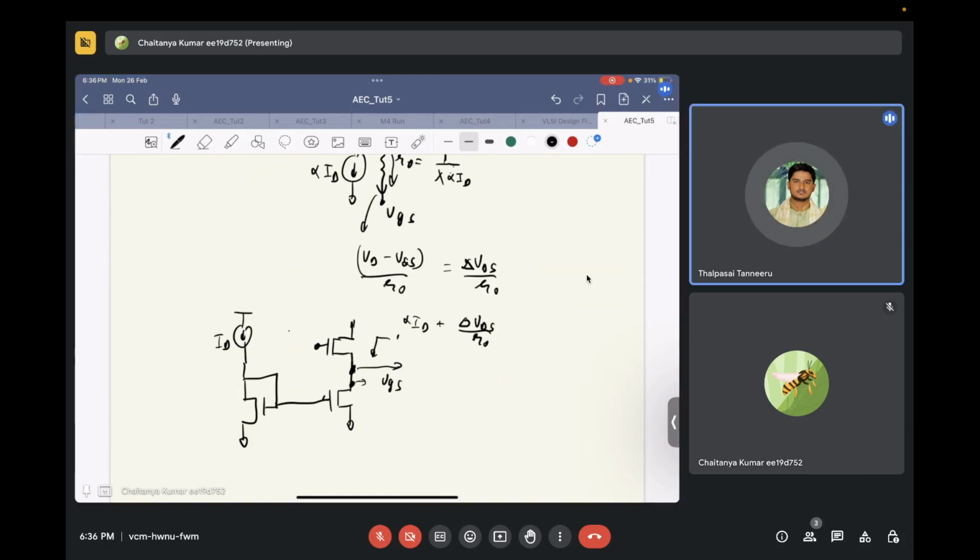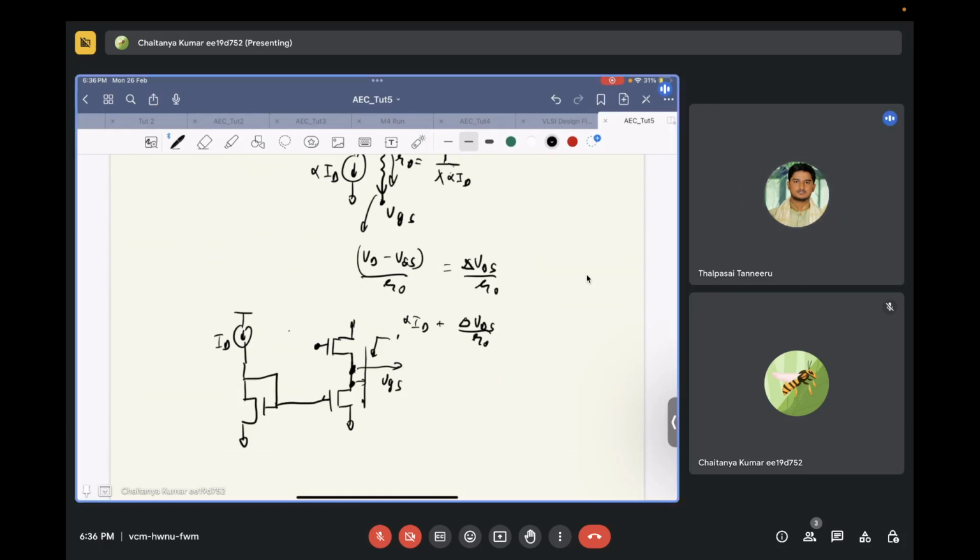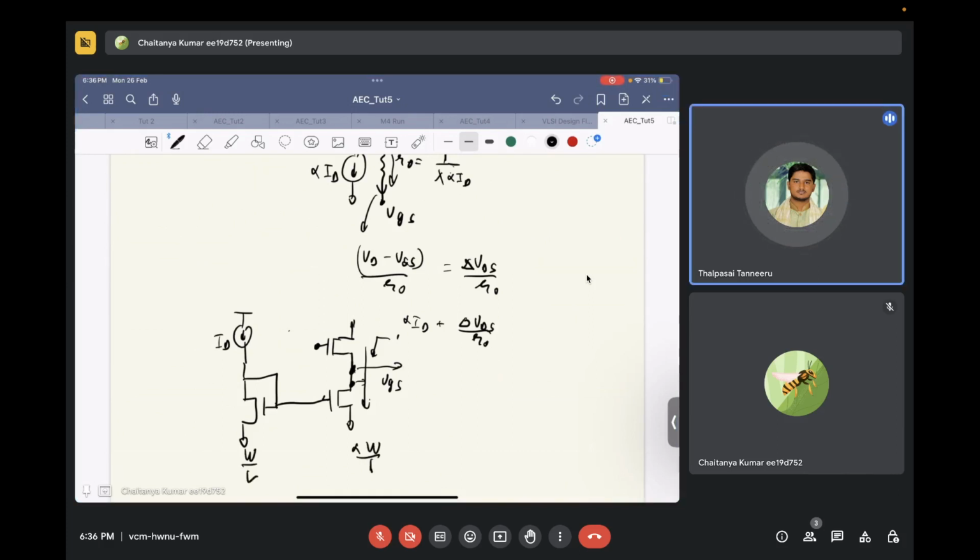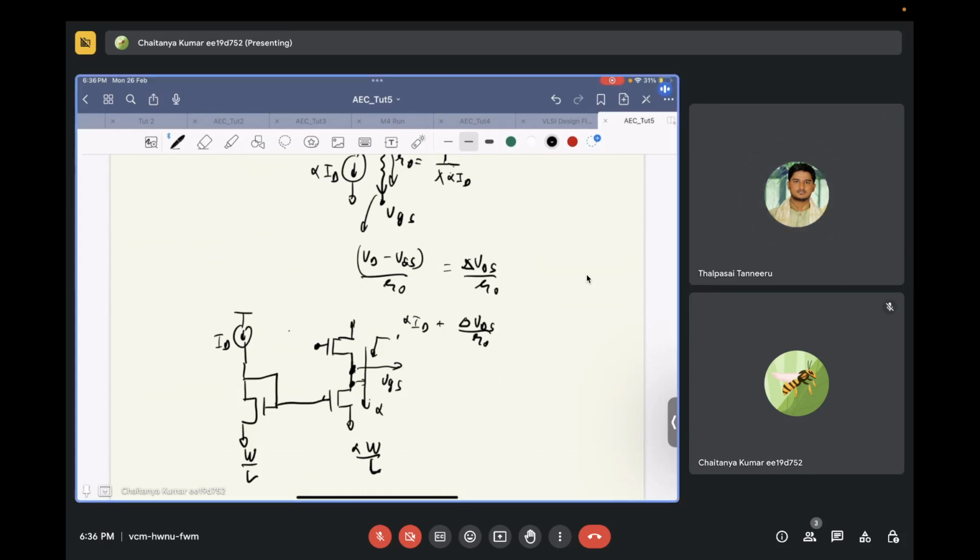Yes, sir. It should be Vs plus, there is calculation also. Gate voltage should be... Okay, what is the nominal current that is flowing through this? ID, sir. Not ID. It's basically alpha W by L. Yeah, alpha times W by L. Based on the diode current equation, then we can calculate it. It's alpha ID that is flowing through this.